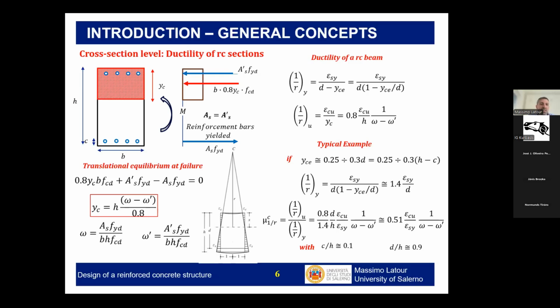In this case, we will see that we have certain requirements which ask us to compare the ductility which is imposed by the seismic event versus the ductility of the cross-section. So here is an example. This is an example of a very simple concrete cross-section, rectangular, with two levels of bars in compression and in tension, made of the same material, of course.